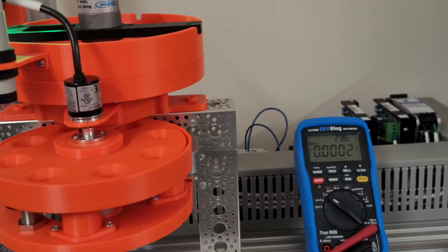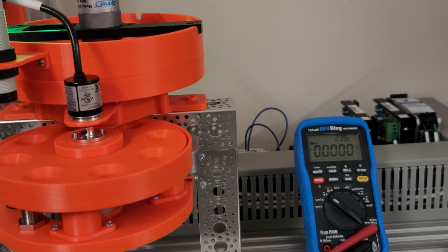I tried to adjust the potentiometer again. It didn't really seem to let me go any higher than the 11.79 value. But it's close enough, and at half it was almost exactly 6 volts. So I think it's adjusted in as good of a way as I can get it right now. I'll have to look and see if there's something else I can adjust. There could be something with the current limit that's keeping it from going any higher, and I may adjust that at a later time, but right now it's good enough for our relative speed experiment, so we'll leave that alone for now. I'm going to stop the motors.